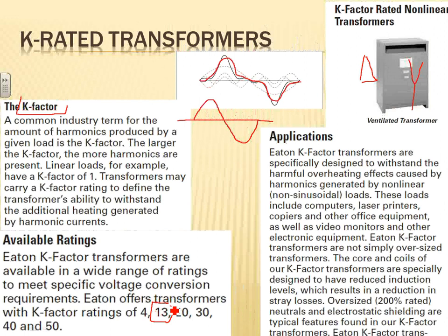These are again from Square D. You can read more about them. Any comments, guys, about K-rated, K-factor or K-rated transformers? When you are having a receptacle transformer, you will make sure that it's a K-rated transformer, K-rated 13 or K-rated 20.